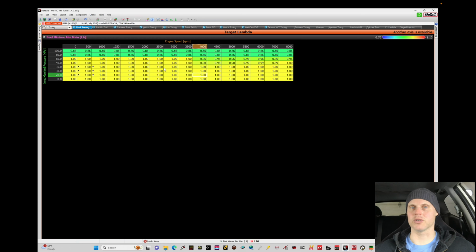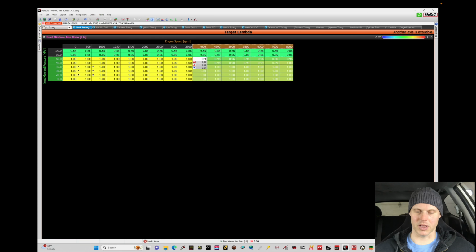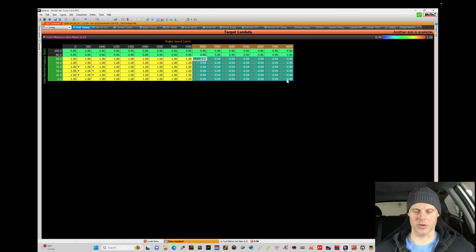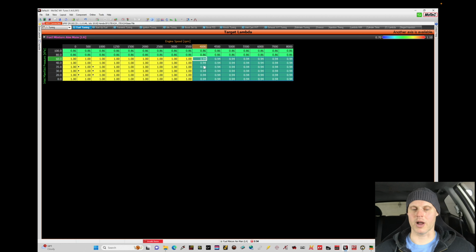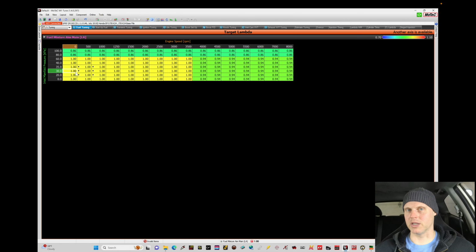Now, when we're talking about alpha-N strategy and doing tuning with individual throttle bodies, it's really a pure race kind of application. So economy isn't the first thing we care about, but we don't want to go in and just be wasteful with fuel, especially if we have to keep track of our fuel consumption during lapping sessions. We don't want to have the values here at something like .86 lambda throughout the entire table. We want to be specific with this. Now, at 4,000 RPM and higher, I'll set this to something like, let's say .94 lambda in part throttle. We want a little bit richer mixture when we're at high engine speeds in our lighter vacuum ranges here. So this table is just pretty basic, just something that we have to configure and set up. So it's going to work here for our setup.